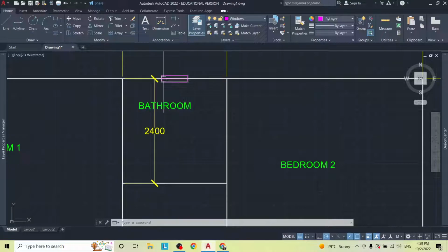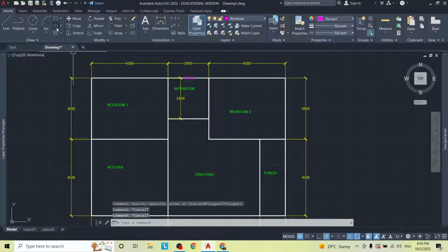So I want to put this right in the middle of that, and there would not be a center line in my walls. I would have to use the top line as my base point and attach it to the top line of the wall. But you'll see when we get there exactly what I mean.